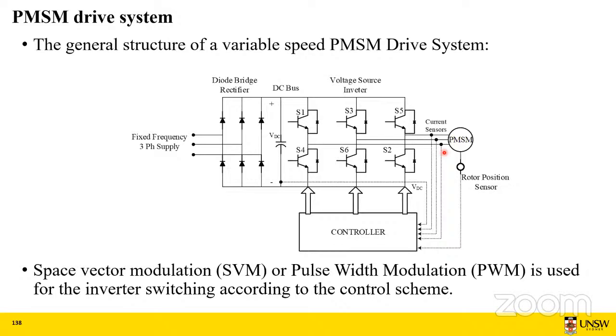So we have discussed the rotating magnetic field, and we have said that the stator gives you the rotating magnetic field, and the rotor has north and south poles. Imagine the north of the stator pulling the south of the rotor, and that's how the rotor starts to rotate, and we get the torque. That's a basic concept, and that's correct.